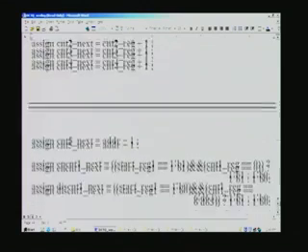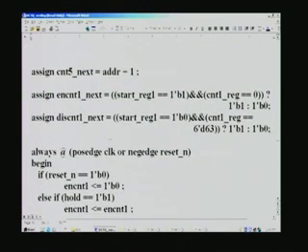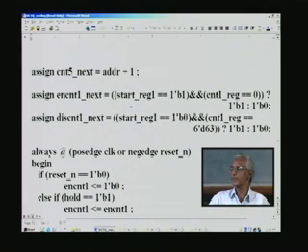And now, the very first counter we should enable only if this condition is met, and it must be disabled when this condition is met here. The first condition is when we give the start signal that the DCT-Q process must begin. Then what happens is, after a delay, this start reg 1, which we will cover at the last of these always blocks in the controller, if it is 1, this is equivalent to start being 1 with a clock cycle delay, and so long as it is 1 and the counter reg is 0, which signals that we are yet to start, right at the beginning.